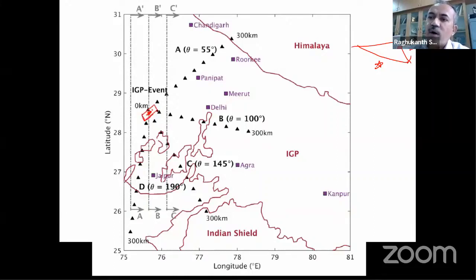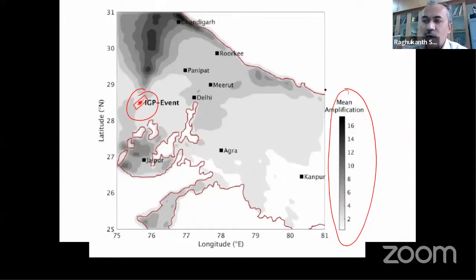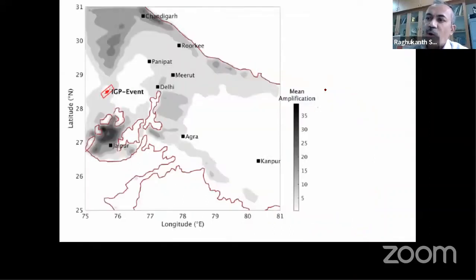This is our finite fault slip model, the Mahendranagar Dehradun fault we have taken, and then we put receivers in all directions, and we try to find out whether any pattern emerges from these simulations. Here also, because it is a strike slip mechanism, we see radiation patterns from our analysis. And here also things get amplified, like 16 times from the rock to the surface. The amplifications are huge. This is, I think, the horizontal component, and this is the vertical component. You can see at far away places we have this amplification also.